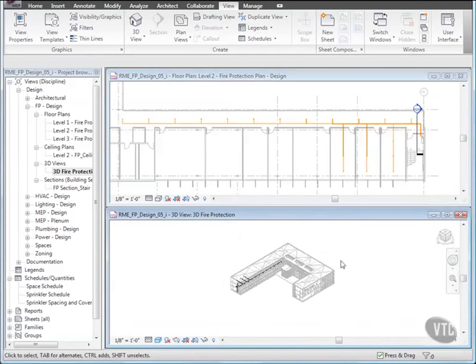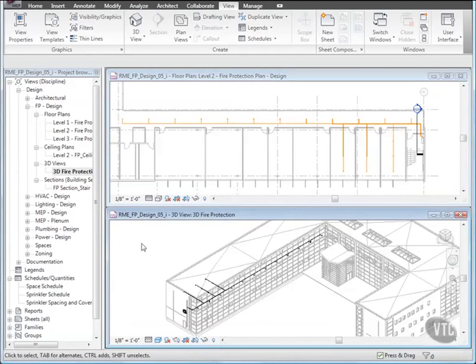It's important to recognize the distinction between sizing and manually changing the diameter, height, or width. Changing the diameter, width, or height of pipe on the options bar is not considered sizing in Revit MEP. Sizing is performed using the sizing tool in the sizing dialog to size the pipe based on a series of parameters and calculations. The calculated size of a pipe is the result of the sizing tool and not the result of a manual change of diameter, width, or height.